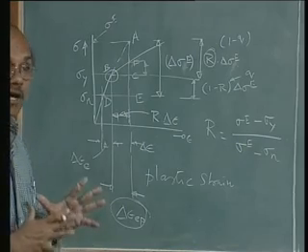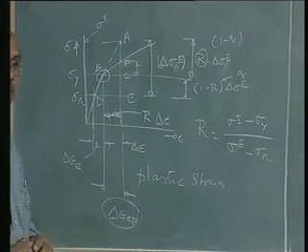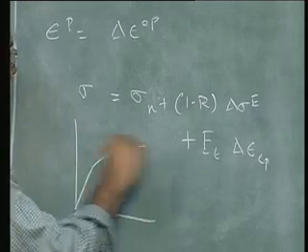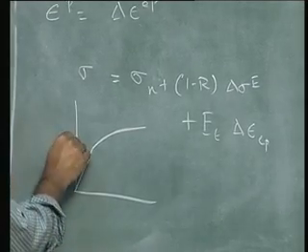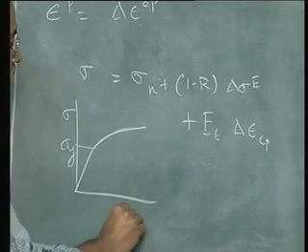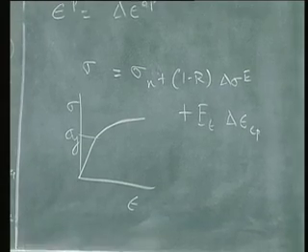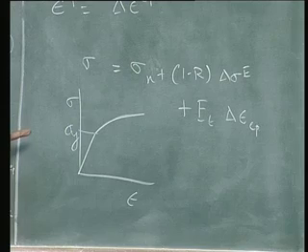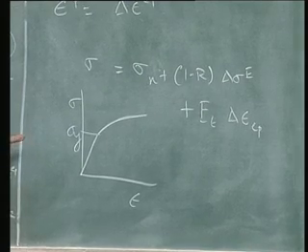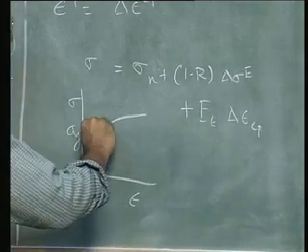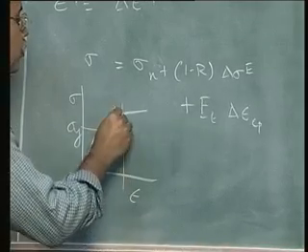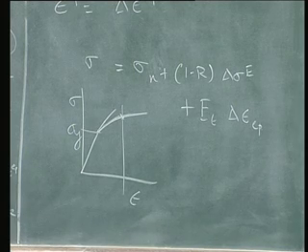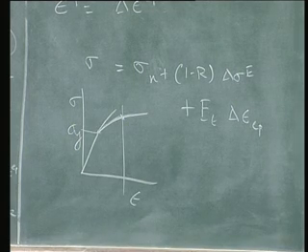In this particular problem we did not have much issue, because we had considered a bilinear curve, but if this curve is not bilinear, what does it mean? It means that my curve would look like that. That is sigma y, that is sigma, that is epsilon, and see that my Et values are not constant in the elastoplastic region, and they keep varying. It may be like this, like this. So, if I have to go to that point, I can have a series of ETs. Then you can ask a question, what ET do I use?